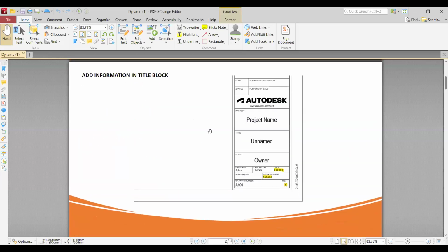In our Revit model, we submit our submissions in the title block. In the title block, we fill in much information like project name and title, client name, drawn by, checked by, date, scale, project stage. If I do it manually, it takes time, but through a Dynamo script we can fill in all the information at once. So I have created a script.